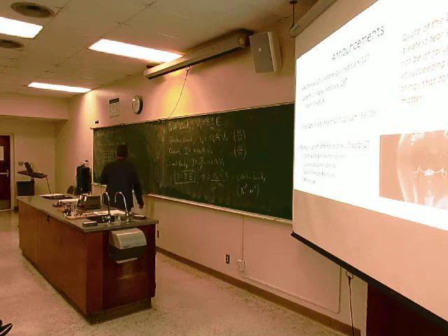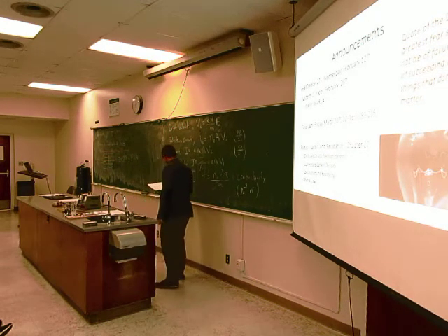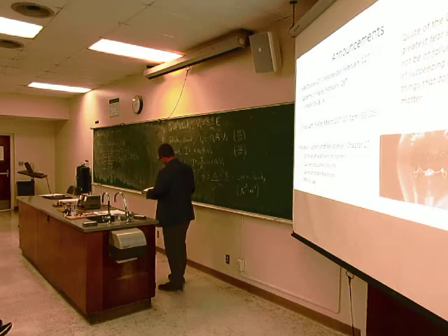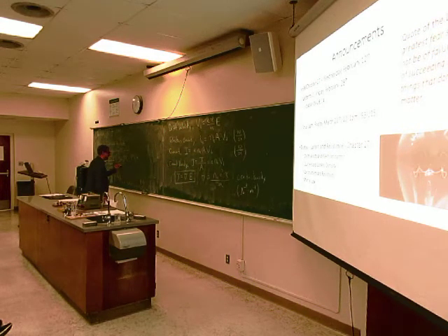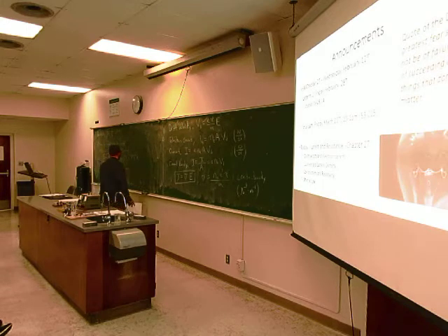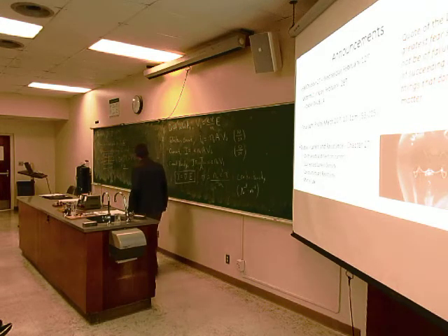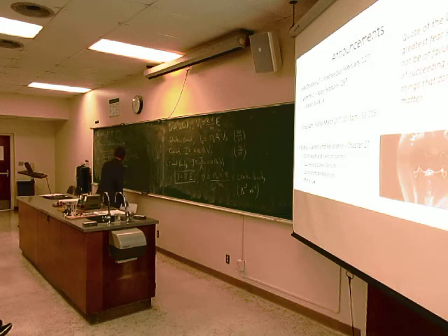And J is just equal to sigma E, so I = sigma E A. And sigma we can write as 1 over rho. So we're going to have a rho on the bottom and A on the top. And then E, I'm going to write as delta V over L.